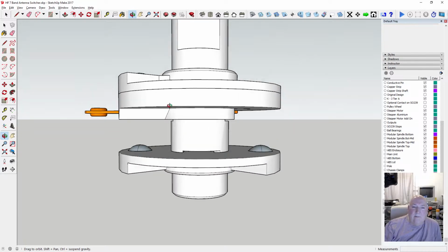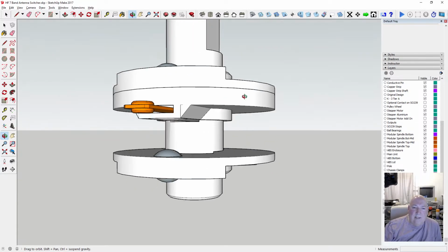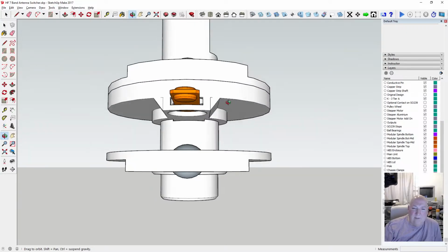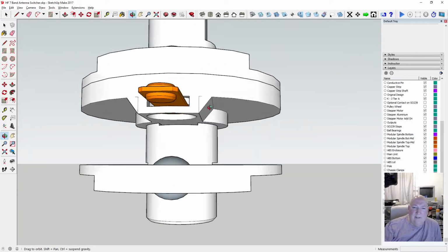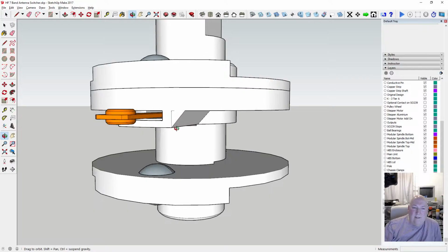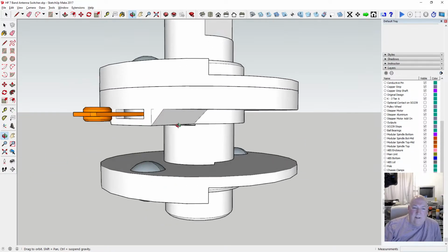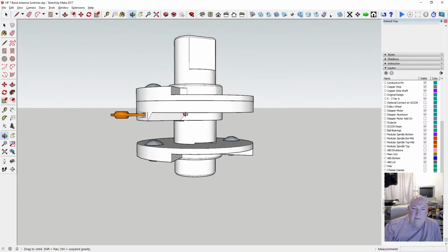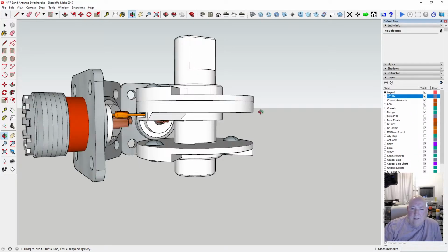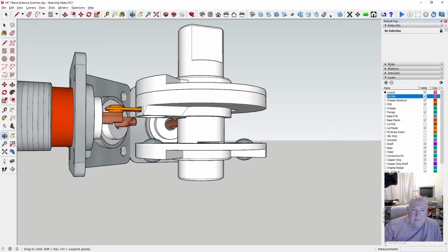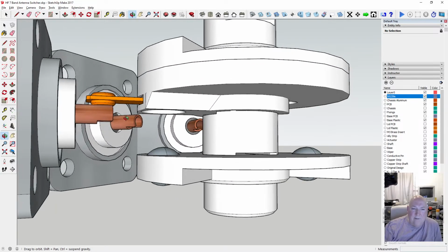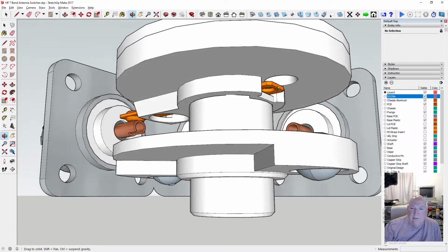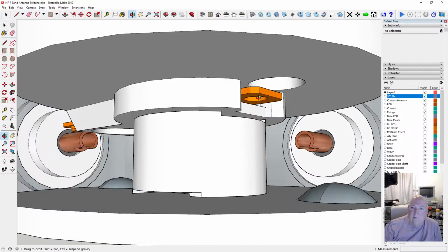Right, so we've got this thing, so we could print that out now, that new one, but the ramp doesn't look enough to me. So you've got to wrap your braid around the SO239s. From there, solder it to there, wrap it round. Which way would you go? Around like that, and then up to there, and solder on there.